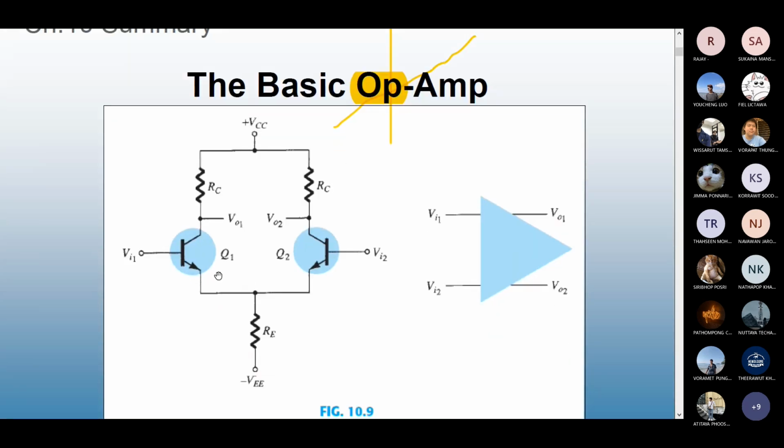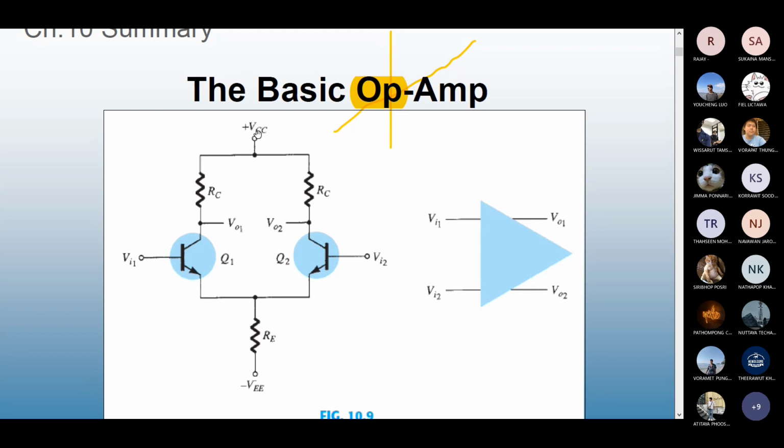You see there are two amplifiers, amplifier 1 and amplifier 2, which are given two names, Q1 and Q2. Q is just the operating point, and they are common emitter. The emitter is on the ground. You can apply a single bias or you can apply two DC biases. So these are pictures of two BJTs. Which terminals are connected? The emitter terminal of the two BJTs are connected. Is this a PNP or NPN?